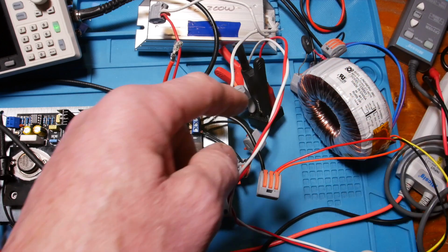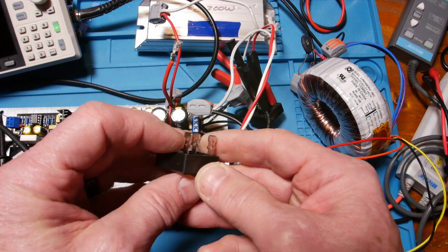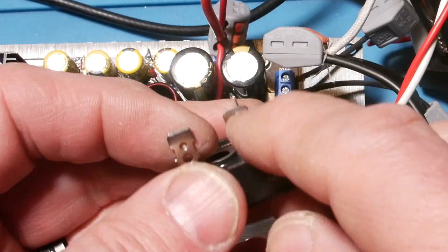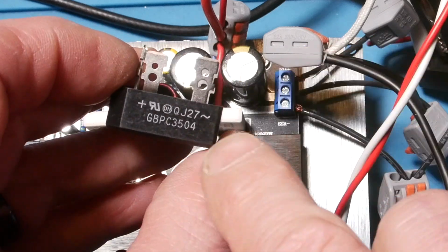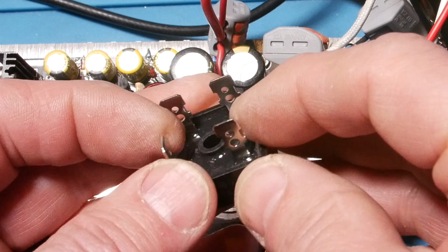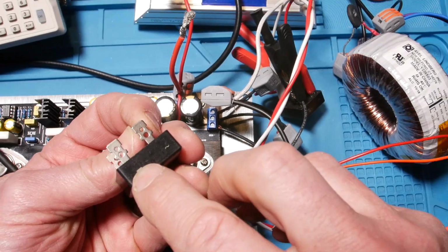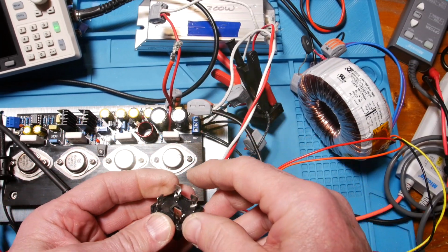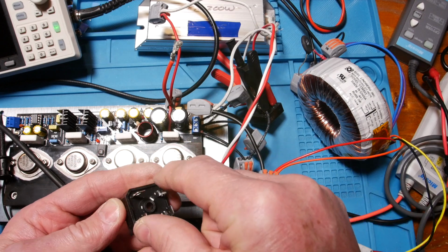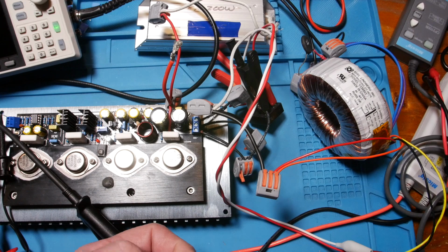And then they go down to the bridge rectifier. And the bridge rectifier looks like this. So you have an AC input on one corner. The opposite corner, you're going to have the other AC input. And then you got your plus. And on the opposite corner, you have your negative coming out. Okay, so it doesn't really matter which two pins on your AC they go to.